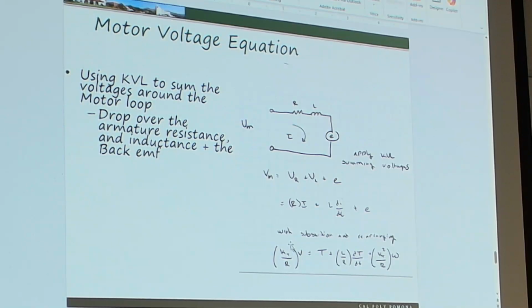So we can think of KT as what creates that proportionality between I and T. Because we know they're proportional, right? Everybody agree? I mean, we saw that before, right? At the very beginning, there was no voltage, it just had current and torque. Proportionality, really, we're coming from that B field for all intents and purposes. So far, so good? So that's the idea behind this expression that we have right here.